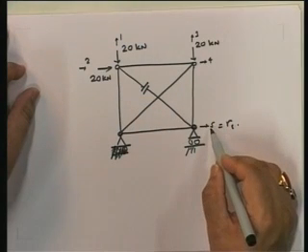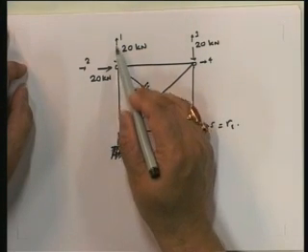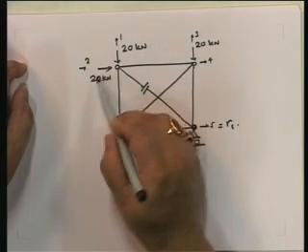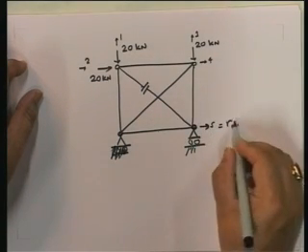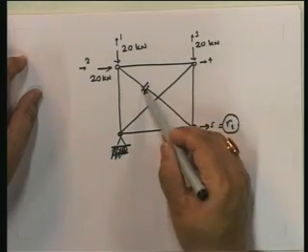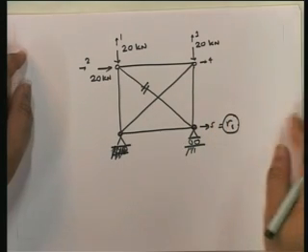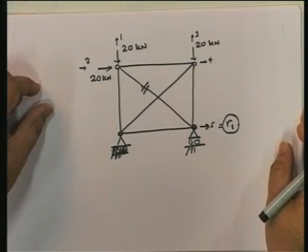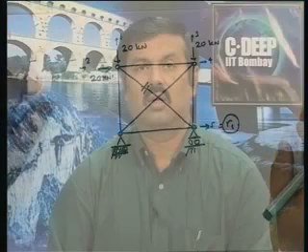Okay. Now, in actual fact, when you actually solved it on the computer, you would consider all these 5 degrees of freedom, and therefore these displacements would become joint loads. However, since I've asked you to only find out this, and this is hand calculation, I can't deal with 5 degrees of freedom plus 1, which is the 6th redundant degree of freedom, and I would have a 6 by 6 matrix that I would have to solve. I'm not quite interested in that particular case.